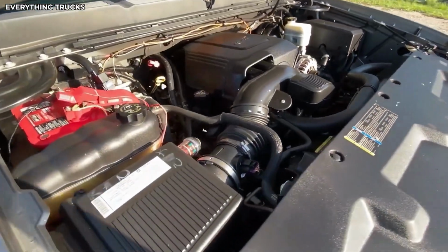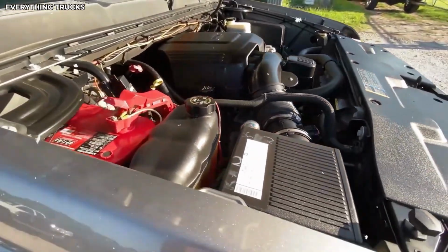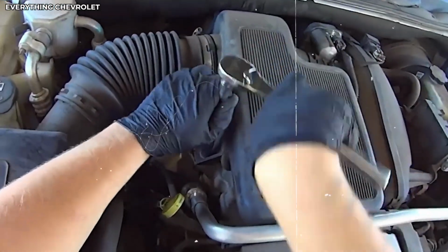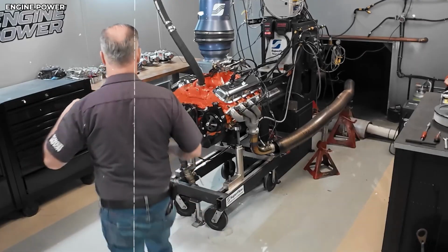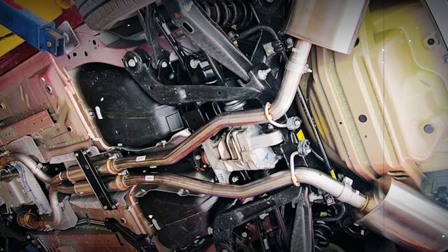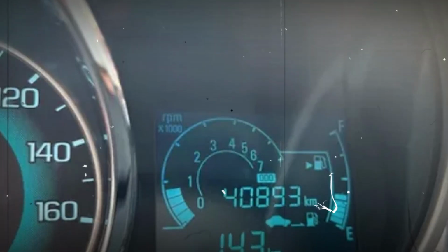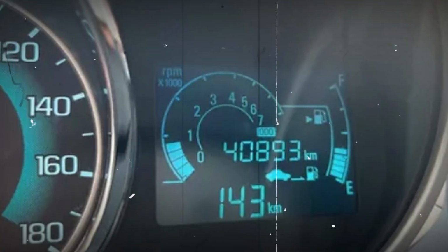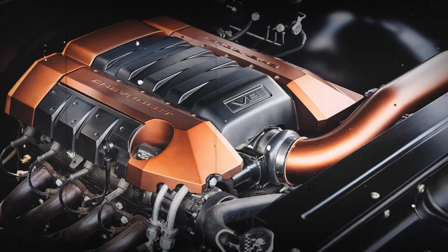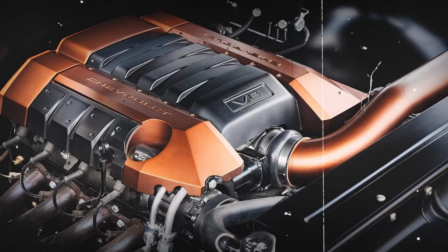For naturally aspirated engines like the 5.0 Coyote or the older 5.4 Triton, the adaptive learning primarily affects throttle response and transmission shift points. For turbocharged EcoBoost engines, it also dramatically affects boost pressure control, making the difference between a truck that feels powerful and one that feels disappointingly weak.